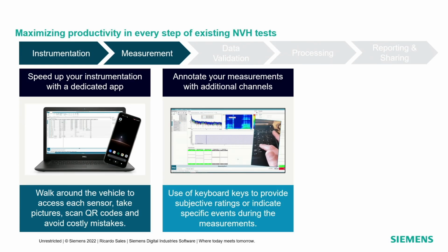During the measurements, also, it's very important to annotate the data as much as possible. Simcenter Testlab offers the possibility to annotate the data with your keyboard. If you have a PC connected during the test, you can use the keyboard to annotate and to inform any event that happens during the test. So the person processing the data will have all the information needed.